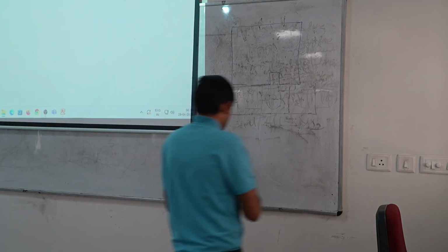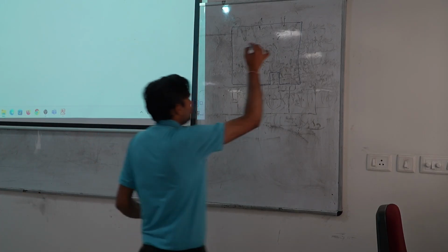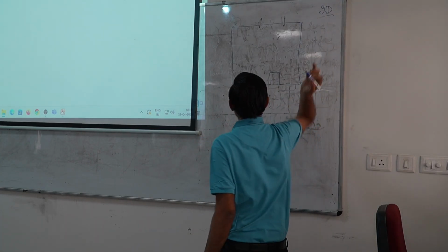Another important point is that whenever we do simulations, we can do axisymmetric simulations, two-dimensional planar symmetry simulations, or three-dimensional simulations, depending upon the nature of the problem. Of course, this situation is not fitting axisymmetry. It may enter into a three-dimensional nature, but a 3D simulation will take a significant amount of time. So at present we will do this simulation in a two-dimensional manner. So, a 2D simulation I will be doing.